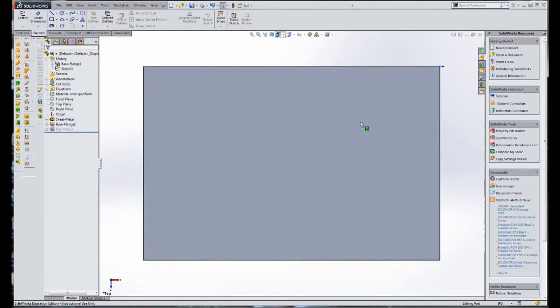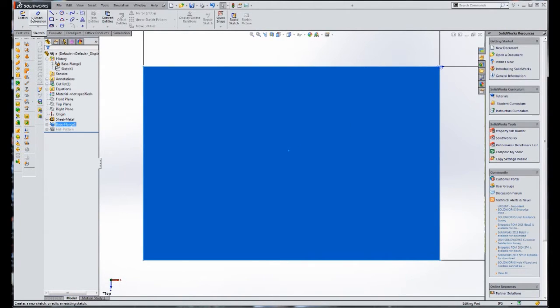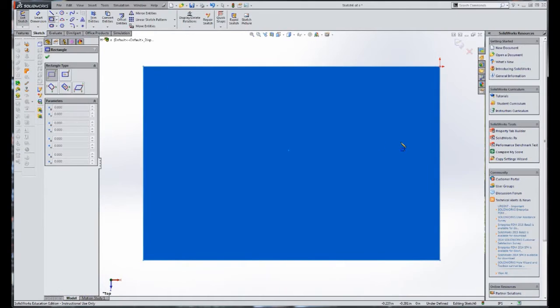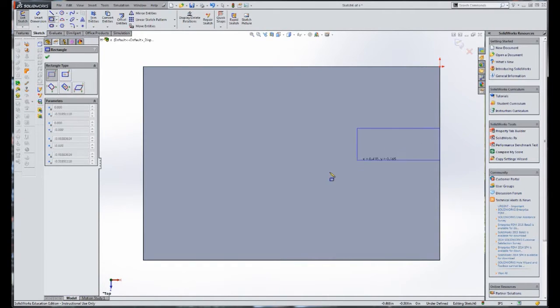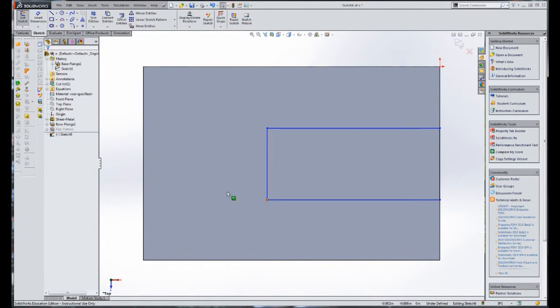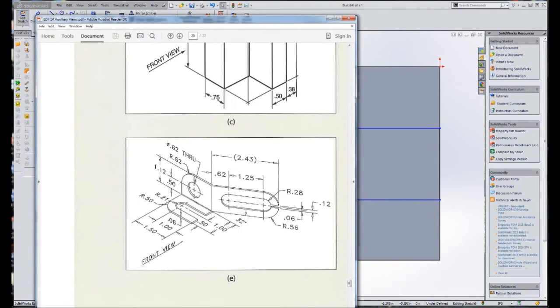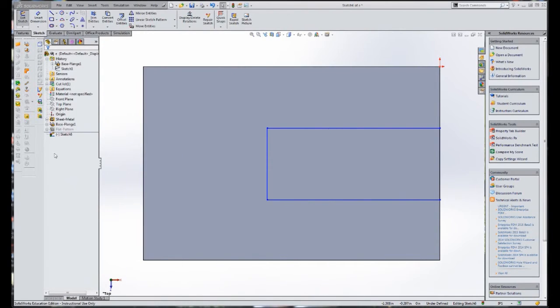And let's go to a top view, and we're going to sketch on here. We're going to do another corner rectangle. Grab the edge, just drag it out. Okay, and what we're doing here is we're going to be doing this slot feature. And also, let's remember that it's 1 inch long, but the slot is also 1 inch plus the radius, which is the 0.21. And since it's 0.21, it's also that in width times 2.